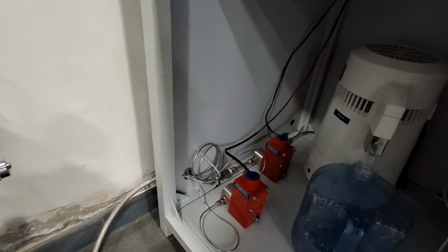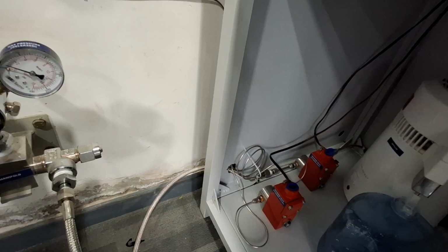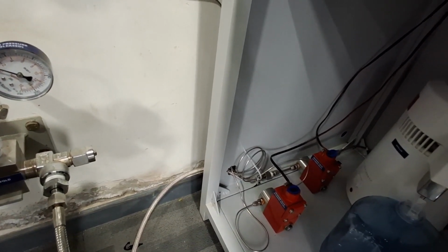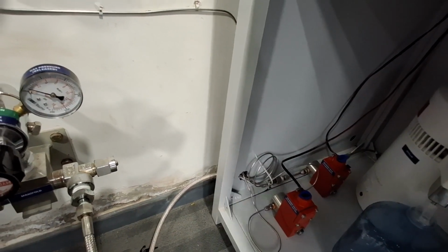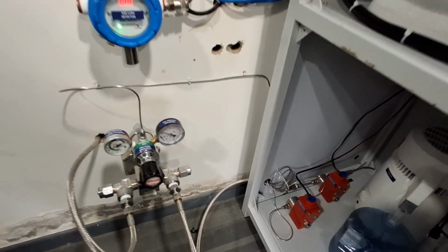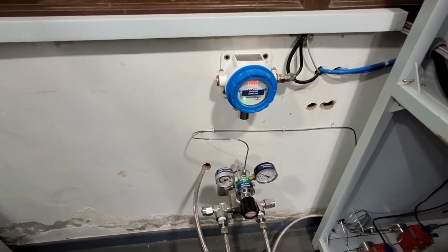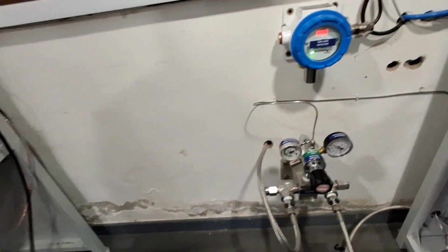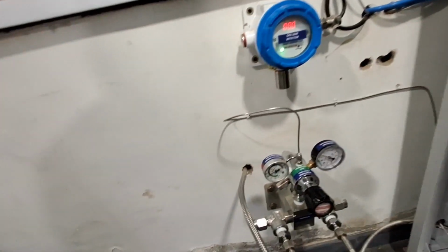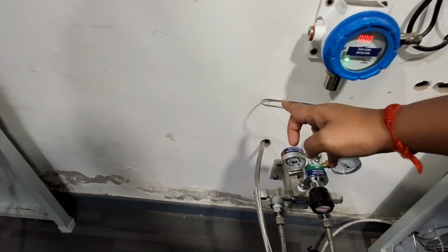We also have two solenoid valves installed at the hydrogen inlet and hydrogen outlet. When the relay is triggered, they also get shut down, and this is a normally closed relay. So we are secure from every point. Neither gas will come out nor gas will go inside the hydrogen tank. This is a manifold. From the gas dryer we go to this point, and from this point it goes to the hydrogen cylinder.